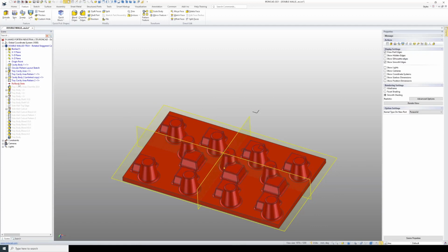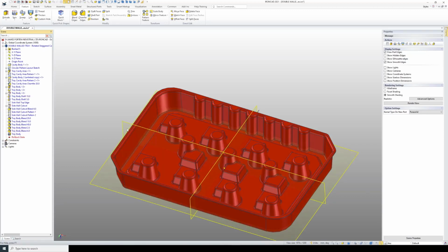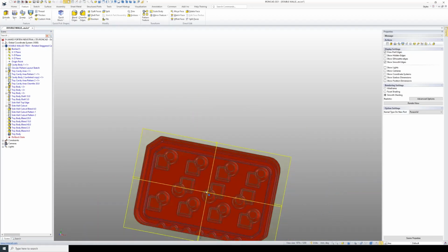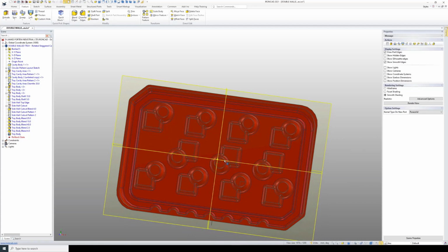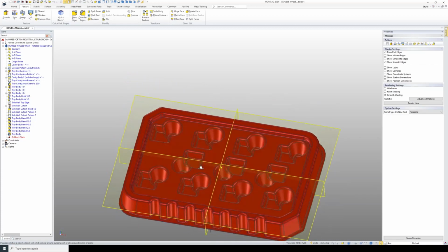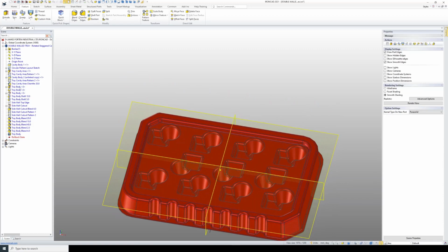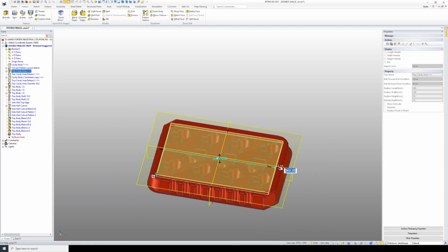So I can roll back our part here back to the end. So right click, roll back to end, and it's fully regenerated. We've got rotated cavities, we've got a staggered pattern. Just like in the other videos, I can select my tray cavity area here and change the values. I'll just manually drag it out, and IronCAD will calculate what can fit within that area.